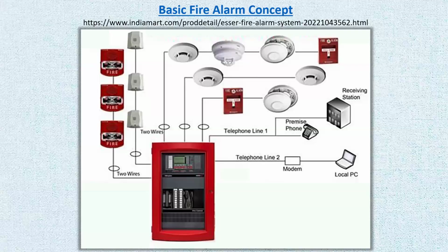What other roles would be associated with the fire alarm technician? There is a lot to do. Annual inspections. Every building that has a fire alarm, and every commercial building has to have a fire alarm, needs to have an annual inspection, and it's a very thorough inspection that involves two people.